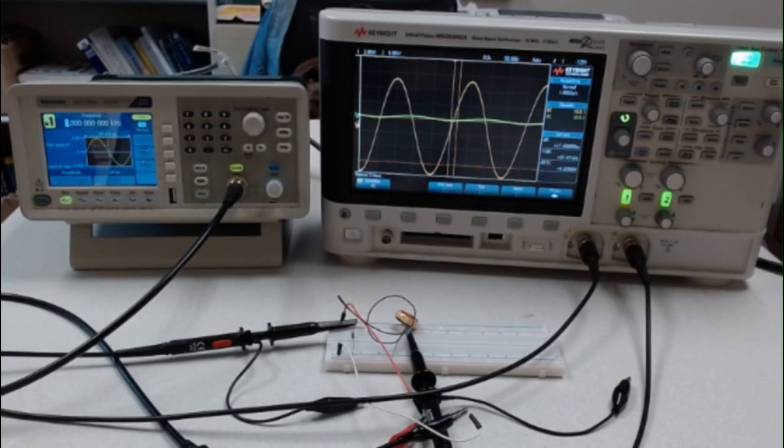So that gives you an idea about this AC waveform. It shifts, and as you get higher in frequency, you get more resistance from the inductor, and the amplitude of the output goes significantly down. So this is a shift and amplitude killer for an output signal, as opposed to the DC, which was a rise and a tau and that type of thing. Now we're away from that, and these are questions that we're going to be talking about in chapters 8 and 9. So take care and have a good day.